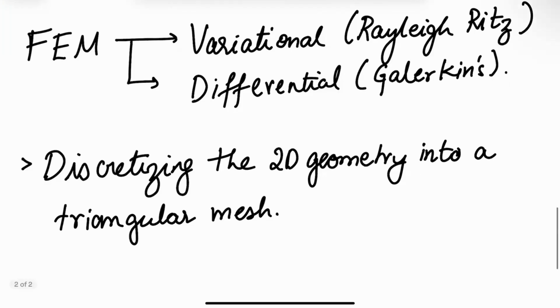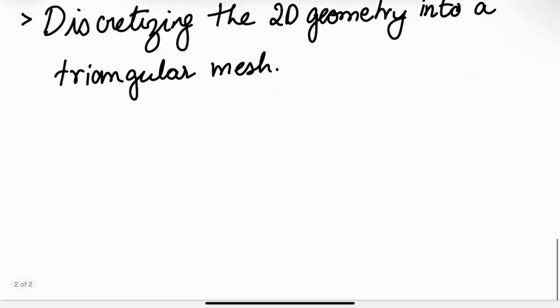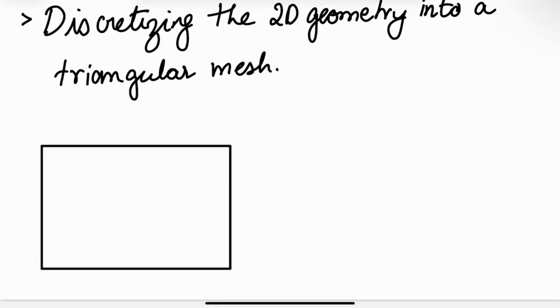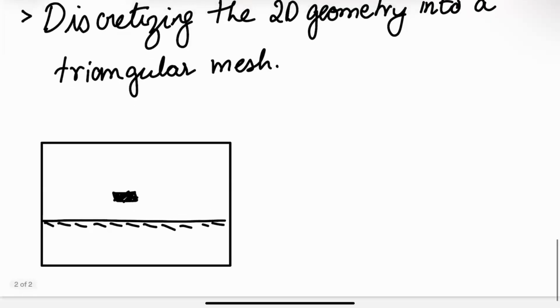Okay, and this is exactly what is happening when you use a wave port. Right? So if I apply a big wave port like this, and I have, I don't know, it could be a microstrip line, which is PEC like that, and then you have PEC out here. Then there is some 2D geometry associated with this wave port, right? That's all of the material that's touching the wave port that provides a 2D geometry. So HFSS is trying to find if this was an infinitely large waveguide, what kind of mode would propagate? And to solve that problem, it uses the Ritz procedure, okay, which we'll look at today.